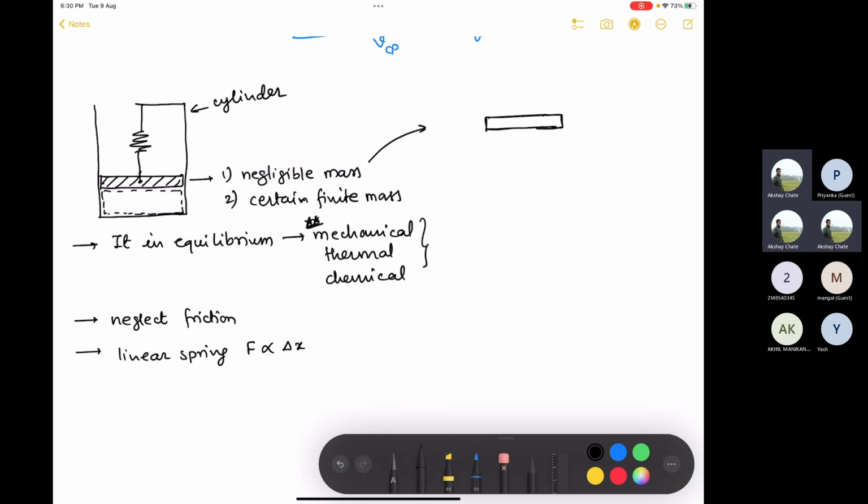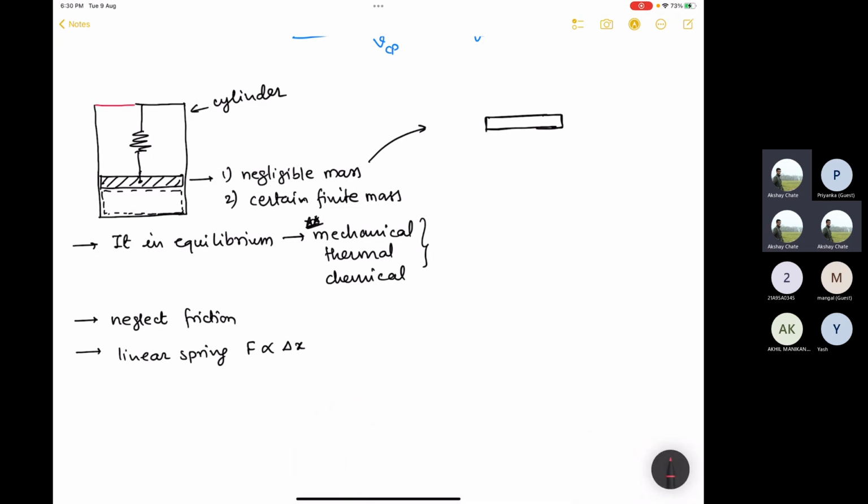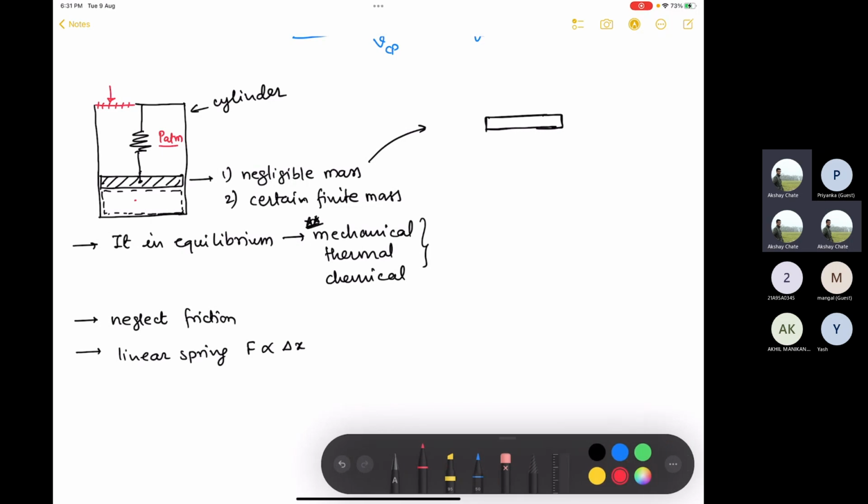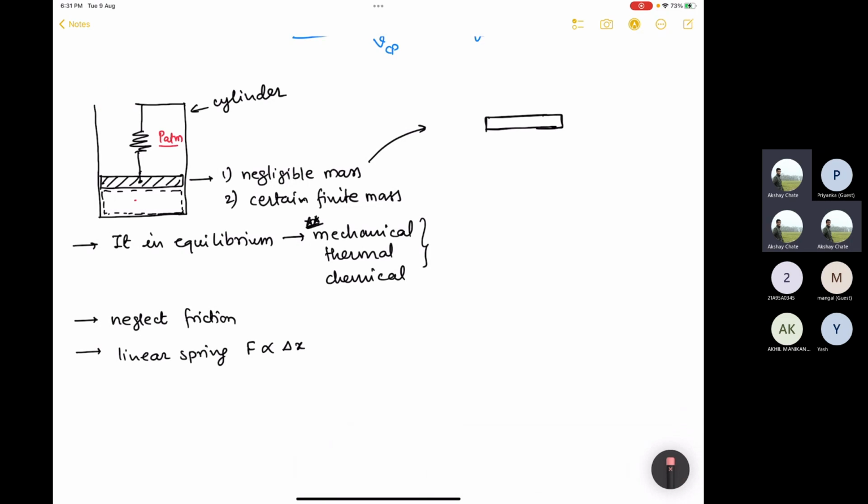And one more important thing is, you should be careful in drawing such diagrams, and not to make the mistake of closing this whole system. I just showed it using the red line, which is shown here. So actually, the point of drawing this piston cylinder assembly with the open edge at the top is to represent that atmospheric pressure is above the piston. If you close this edge using this red line, that means that is not atmospheric pressure anymore, because if your system expands, this part will compress and it will be higher than atmosphere, and vice versa. So what I have seen sometimes students do, in the haste of time, is close this edge as well. So don't do that. You just keep this open, so that represents there is atmospheric pressure above the piston.